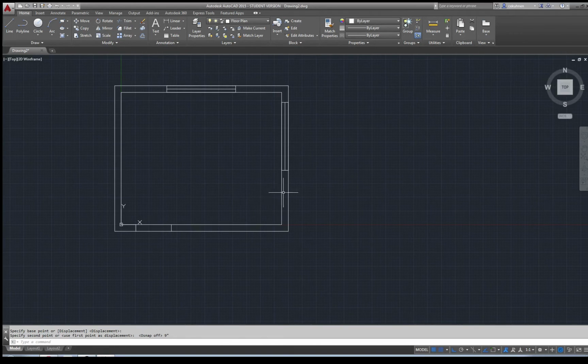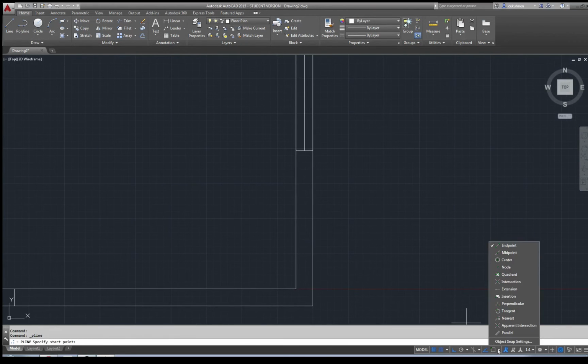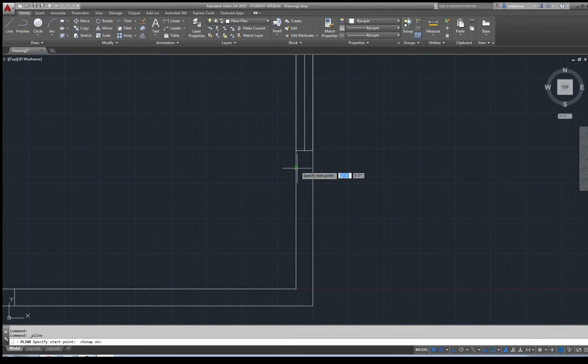In here I have a small interior wall. So for example, the wall is 38 inches wide and then 28 inches long along this distance. We could use the poly tool. I go to somewhere, but I would like to snap right onto the wall. So I turn on, for example, nearest. Snap. Click this direction, 38 inches, enter, move my mouse straight down, 28 inches, enter, escape.